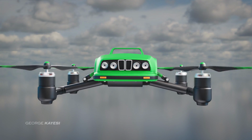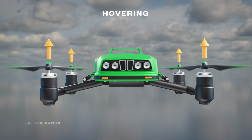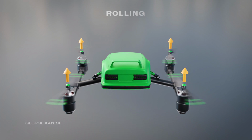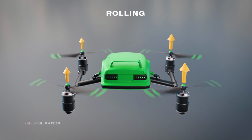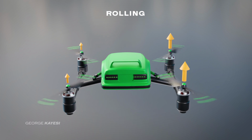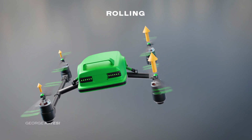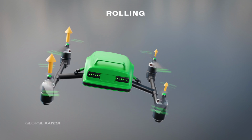Once airborne, the quadcopter will need to hover. To do that, the upward force needs to match its own weight to achieve equilibrium. In order to roll to the left, the quadcopter increases power to the motors on the right, which increases their thrust, and decreases power on the motors on the left, to reduce their thrust. The result of that force will roll the quadcopter to the left. In order to roll back to the right, the quadcopter simply reverses the process.